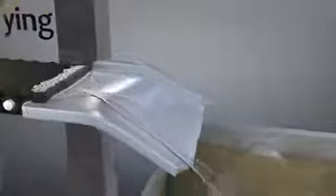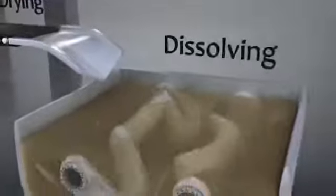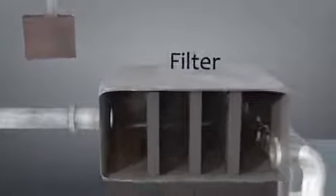The PAN passes through a drying step and is dissolved in a carrier solvent. It is then pumped and filtered. The PAN is extruded through a die into a solvent bath to form the filaments that appear here in fine strands.